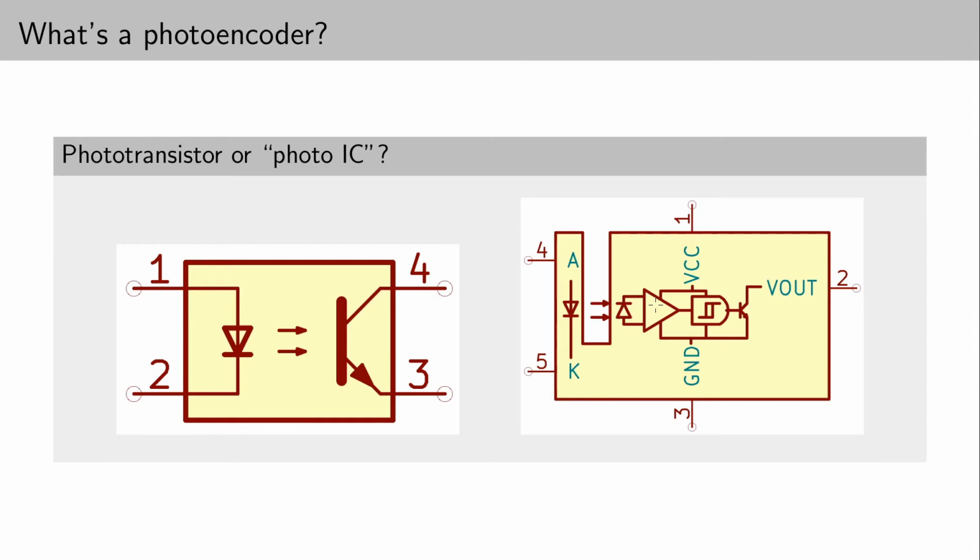And that's nice, but I think that it's probably not suitable for our situation, because I believe it relies on having a good difference between the unoccluded and the occluded state of your optical beam. You need to go between completely unoccluded and completely occluded. And we're not quite going to be doing that because of the constraints on manufacturing this encoder disk that I mentioned last time.